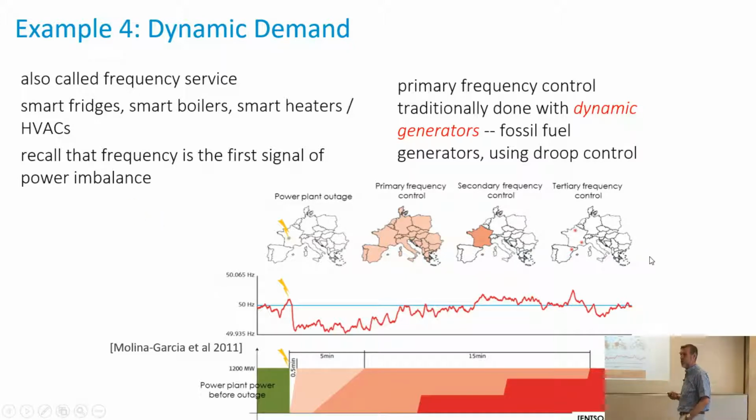Now what happens when you have in June a lot of sun and wind? Then it may be that in Northern Europe, for example, up to 50% of energy is renewable. And we hope in 50 years, perhaps 100% of the energy is renewable. Then we need more of this. We need more of the reserves. The fluctuation will be much larger. So a side effect of renewable energy or randomization of the generation is the need for more reserves.